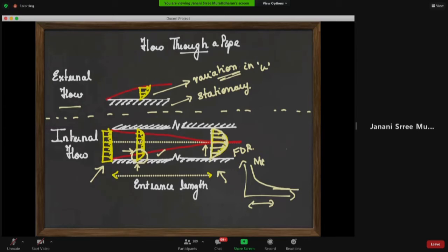thermal boundary layer temperature difference is quite large. The profile of your velocity, the transport, is quite steep. There's a lot more gradients that's involved, and so on and so forth. So the idea here is to say that in some cases, industries prefer to operate in the entrance length region, which means you have to prolong the entrance length behavior in some cases.